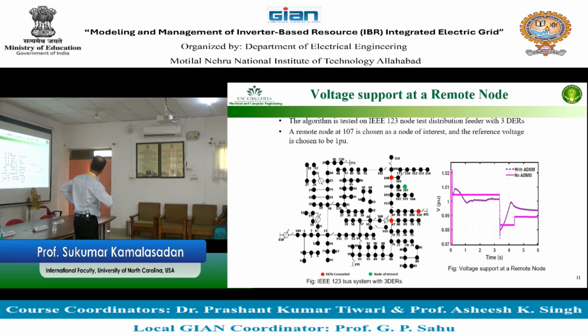So if this voltage is low, this voltage regulator will feel the voltage here. This voltage regulator only looks at this point and this point. Remember that? I told you, we will not look at any. So if this voltage is low, this voltage regulator will tap. And if we have a DER here, DER also will push reactive power. That is coordination. Now you need to make sure that these two are working together. Otherwise, you have a problem.